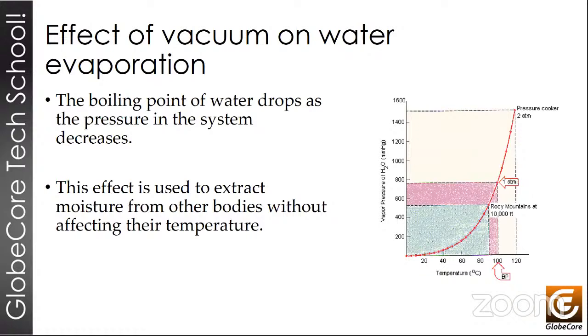Thermal vacuum is by far the most common method for dehydration of transformers, because it's a highly efficient process and there are no consumables involved, such as absorbents. The thermal vacuum process uses the difference in physical characteristics of water and oil to extract that water from the oil.